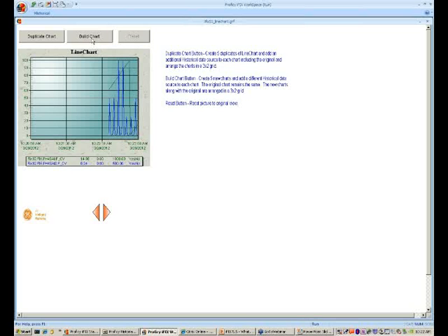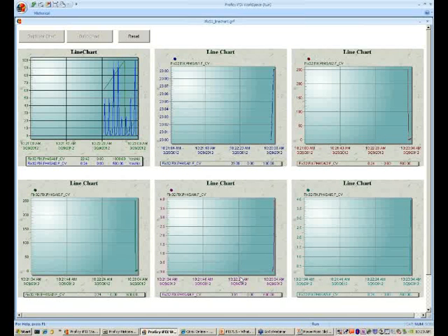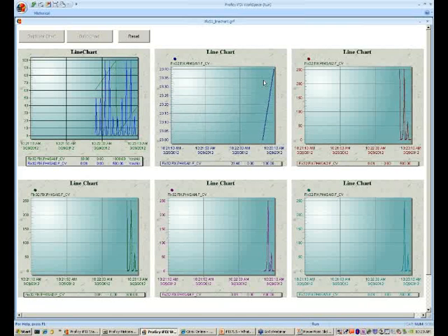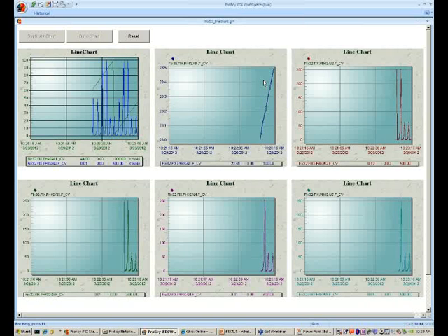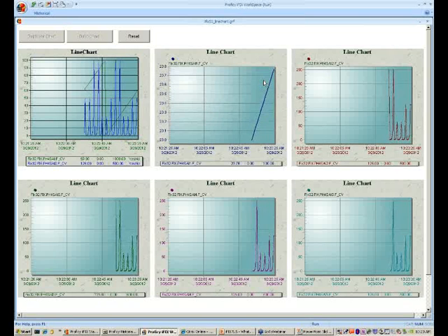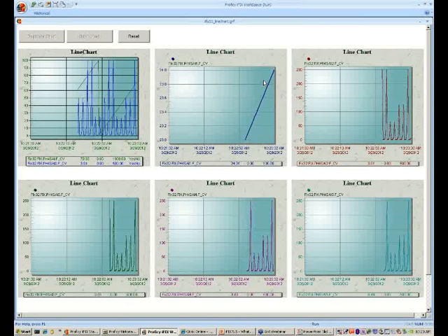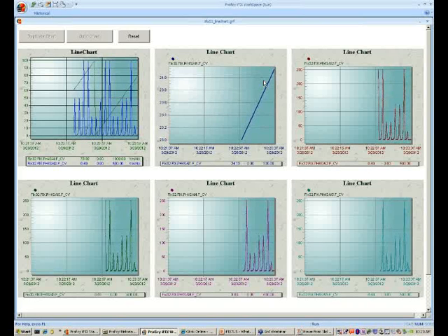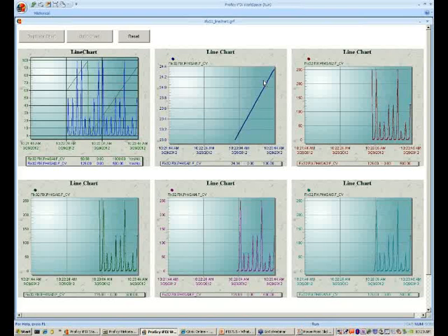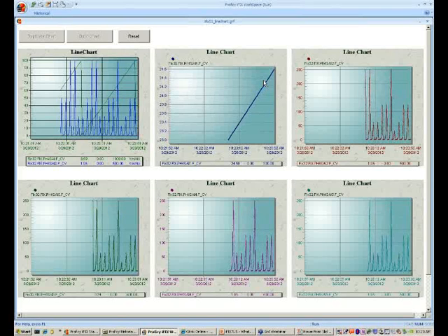So when I say build chart, it just makes a snapshot of this chart and then lays out the chart for you. So this is, again, I'm in run mode. Don't have to go into the configure mode when I do that. For an operator, if he wants any special kind of charts that he wants to generate based on a particular situation that he wants to study, he doesn't have to go into configure mode or call the engineer to say, I need another chart that shows me this information. He can do that while he is in run mode as well. Now, you can't save it, or to save the chart graphic, there's certain advanced scripting that you need to do from a workspace standpoint. But as far as the operator is concerned, he can basically initiate this as and when he wants, on demand, as he is looking at his information.